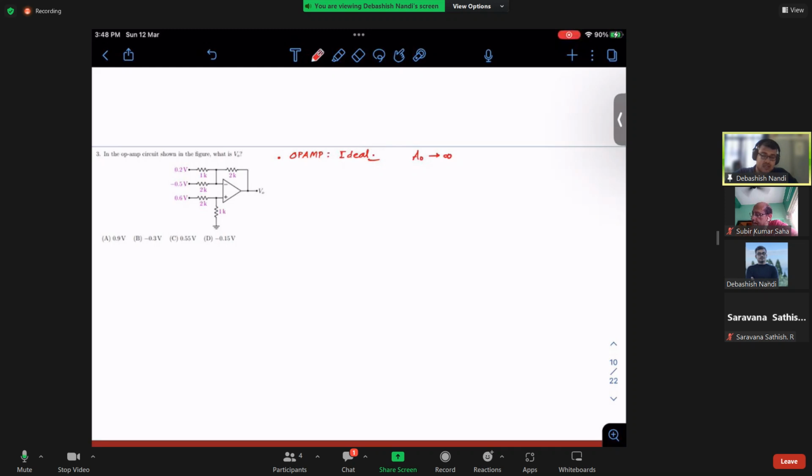See, I have mentioned one thing, that this is for a negative feedback system. And why do you need your negative feedback system? To gain stability, right? Now suppose you want an amplifier, and you want a particular gain of, let's say, K. You want your V out to be K times V in, right? How can you go about this? You can simply set it at K, but then if somehow your input gets changed, and you do not have control over your input, then what will happen? Your output will not be stable. It will keep toggling, right? And you will not have any information about your output at the input side.